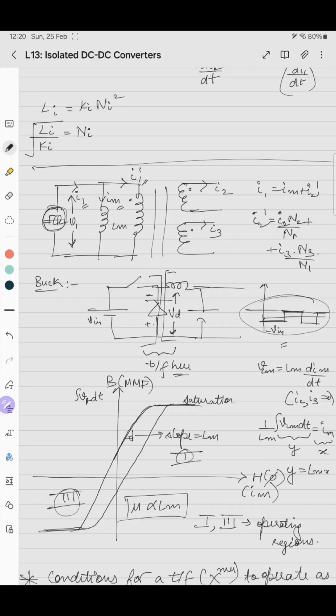It should be zero average value, otherwise the transformer will be saturated, which means that instead of giving a sinusoidal component, we are giving a square wave component which has harmonics of n order.